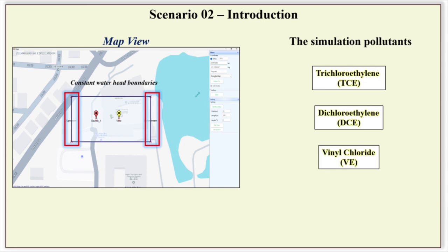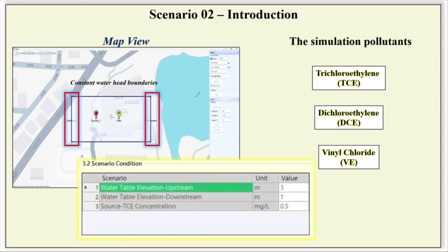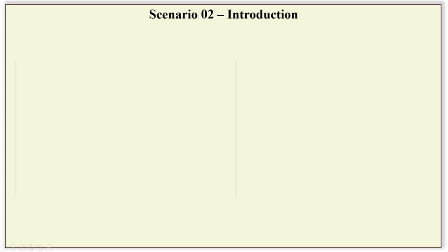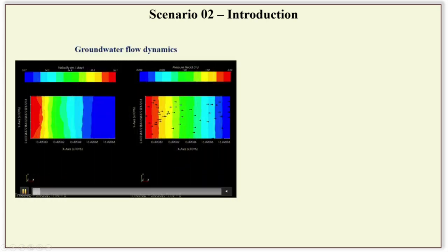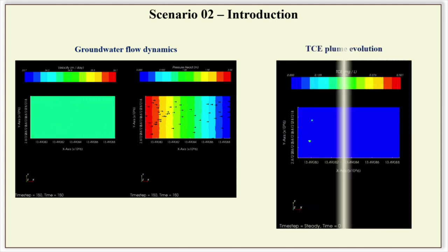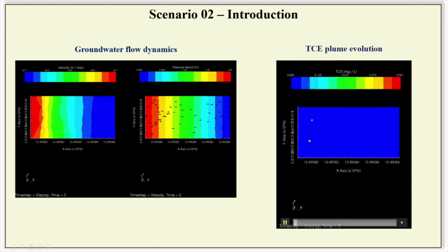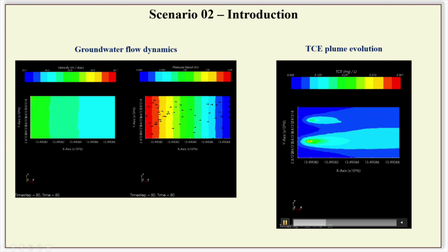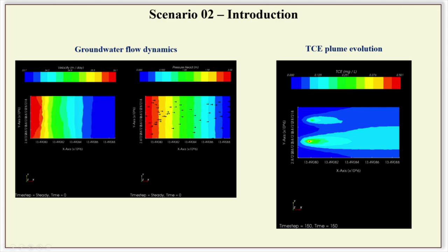The model simulates dissolution, adsorption/desorption, and other geochemical reactions. Users can adjust the contaminant distribution at the boundary and modify the initial concentrations. After running the simulation, the model produces results indicating changes in aquifer conditions, saturated and unsaturated zones, and groundwater flow dynamics. With the coupled chemical transport module, the simulation can provide insights into how contamination plumes evolve over time due to groundwater flow, helping users assess potential impact zones.